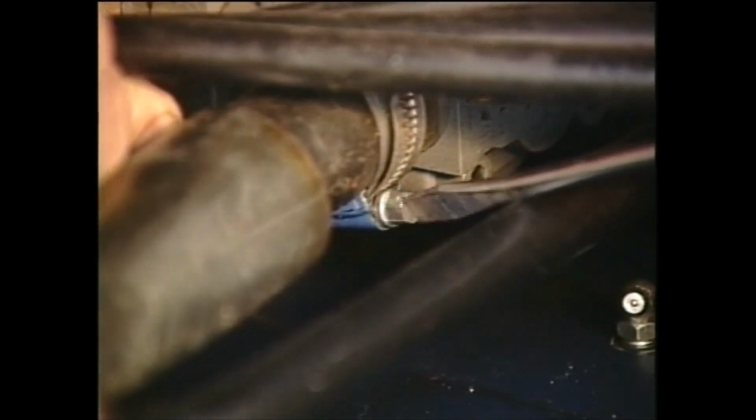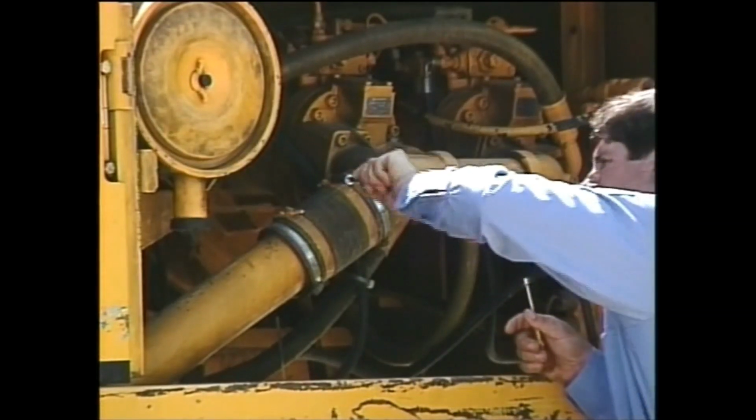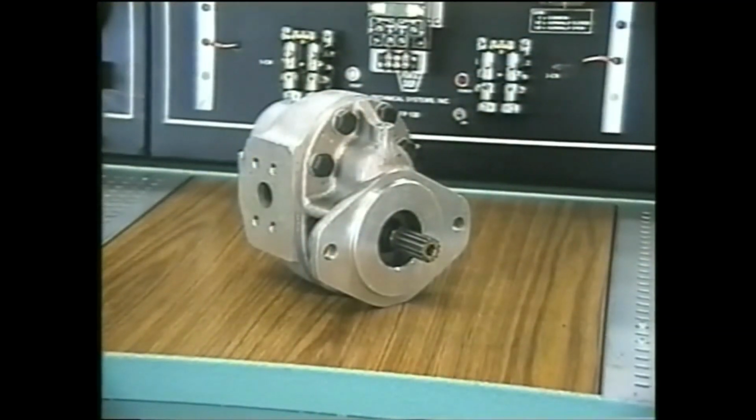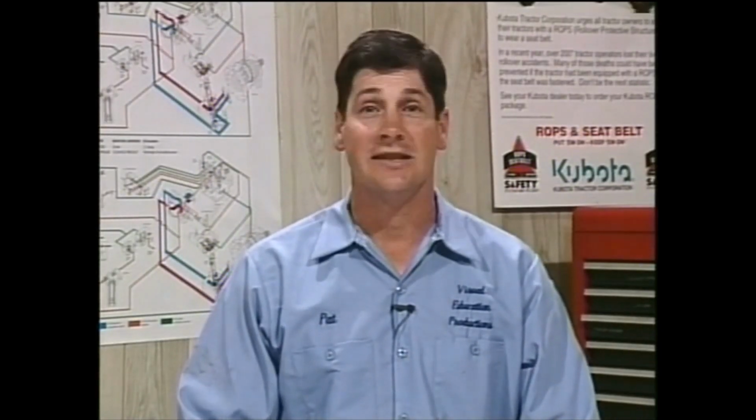Another problem occurs when air enters the hydraulic system on the suction side of the pump through leaky fittings or pump seals. The vacuum created from a hydraulic pump is so strong it is capable of pulling in air through gaskets and seals that do not appear to be leaking on the outside. Aeration resulting from incoming air can be just as destructive as the cavitation from the vacuum vapor bubbles. Additionally, air in the system slows down a machine's cycle time.